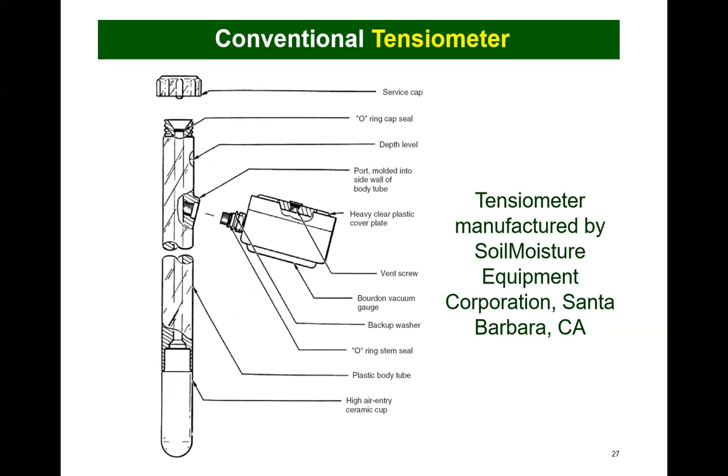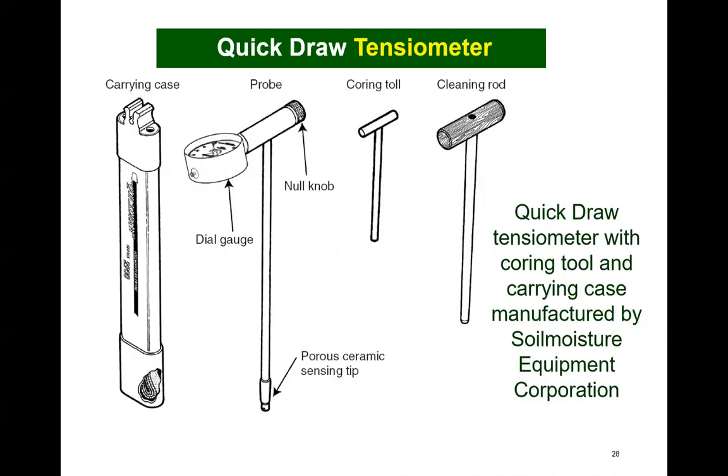Each tensiometer should be serviced prior to installation to ensure that it can sustain a tensile stress in the water phase of at least 90 kilopascals. Servicing may also be required on an almost daily basis if the suctions are to be maintained near the capacity of the tensiometer.